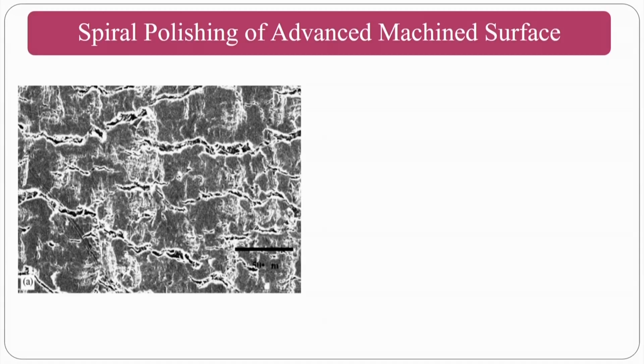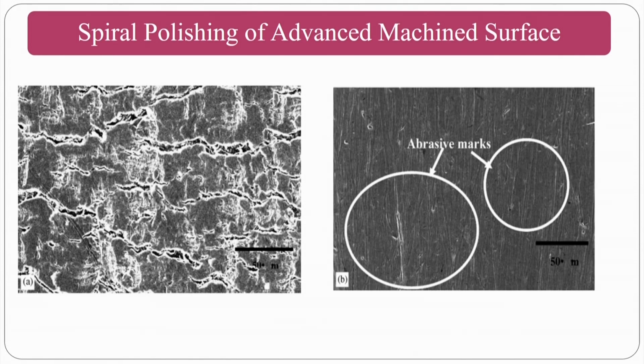If you are happy with micro surfaces, 2 microns, 1 micron, or 1.5 micron, then grinding is a very good process. If you want 50 nanometers, 100 nanometers, 75 nanometers, then you obviously have to go to the advanced finishing processes, and one of them is the polymer assisted abrasive finishing process, which is the course that I am dealing with. The spiral polishing method also, some of the methods will use the EDM process, electric discharge machining.